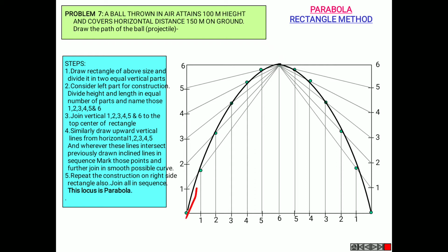So this is our required parabola. Okay, now the next method is drawing a parabola by triangle method or method of tangents. So similarly, not moving into the theoretical concept, we'll directly move into the problem. Draw an isosceles triangle of 100 mm long base and 110 mm long altitude. Inscribe a parabola in it by method of tangents.